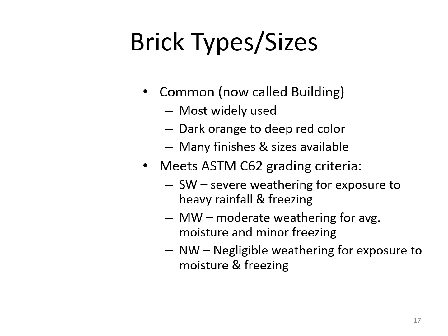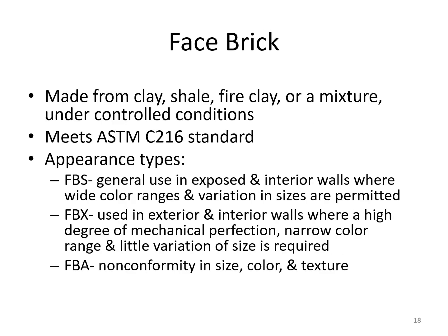Let's say that's in the southwest. SW would be used in the north part of the country. And then you have NW, negligible weathering, for exposure to moisture and freezing. So that's in the real temperate climates, maybe the tropical type climates as well. So face brick, this is another type. It is made from clay, shale, fire clay, or a mixture under controlled conditions. That meets the ASTM C216 standard.